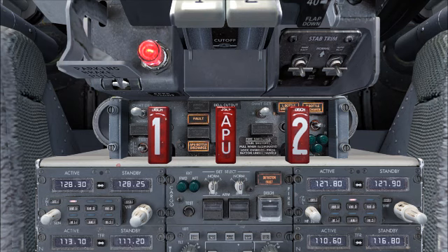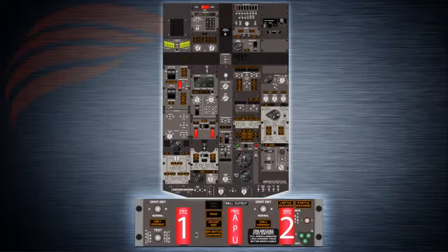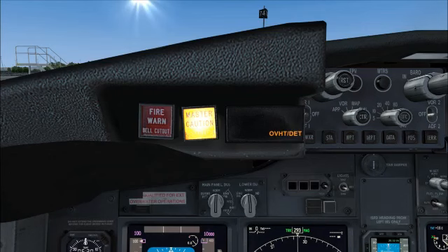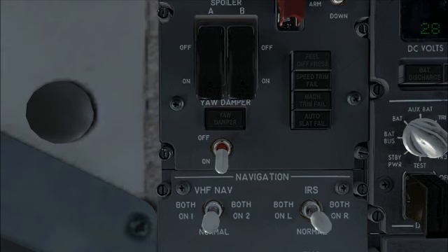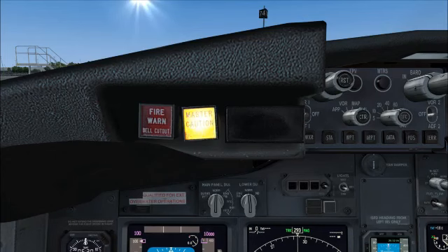So, to reaffirm which lights do trigger a master caution, all amber lights on the forward and aft overhead panels will trigger a master caution, and the engine 1 and 2 overheat and APU detector inop lights on the overheat fire protection panel will also trigger a master caution. Whenever any one of the system annunciator panel lights illuminates, the master caution lights will also illuminate. As we said before, the master caution system is for all intents and purposes an attention getter that directs crew attention towards the problem area concerned.